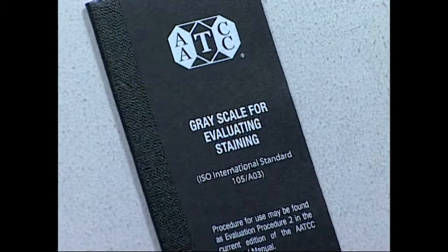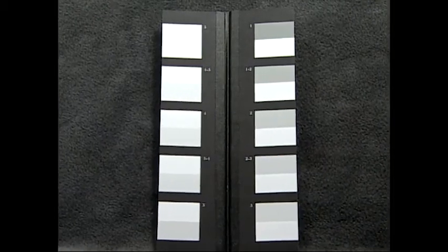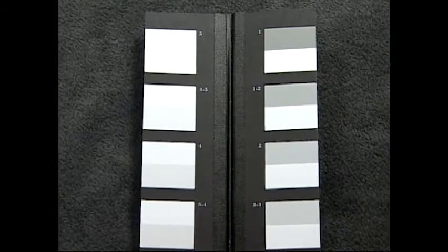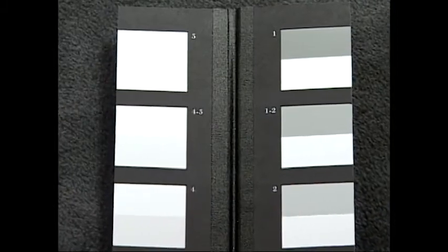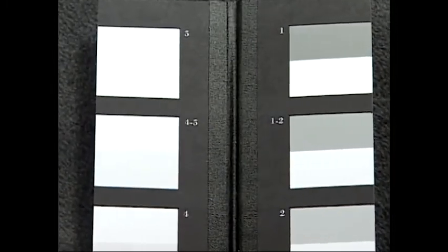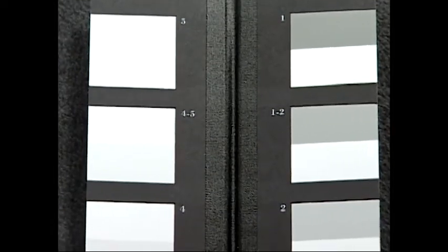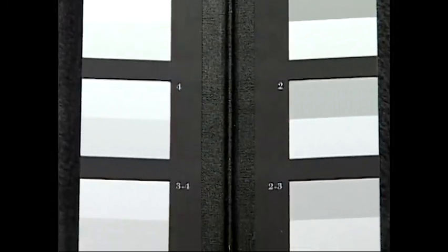Another procedure is the AATCC Evaluation Procedure 2, Grayscale for Staining. This procedure allows for evaluation of staining of undyed products during color fastness testing. Staining is the unintended transfer or pickup of color to the sample from 1. exposure to a colored or contaminated liquid medium, or 2. direct contact to dyed or pigment-colored material when contaminant color comes from mechanical surface action such as rubbing or direct sublimation. This grayscale consists of white and gray chips or tiles with the level of contrast in gradients. It's used primarily to measure staining for laundering, accelerated laundering, and crocking.